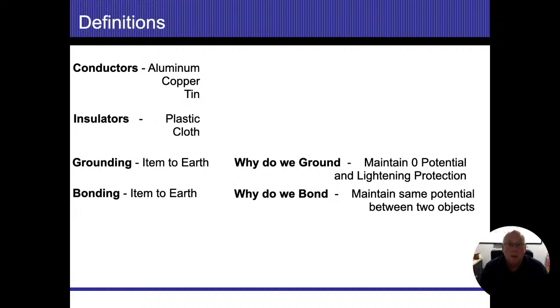It's wasting our bill. In fact, that's called a fault, more specifically a ground fault. Anytime electricity goes someplace that it's not supposed to go is considered a fault. And if it goes into the earth, we call those ground faults. All right. And I usually pop up another example, like I'll take a wire and I'll pretend that we're going to put this into the energized slot of an outlet. And let's say it's a 15 amp outlet. And then I'll take the other end and I'll go outside and I'll have a ground rod out there all by itself in the middle of the yard, driven into the earth, a good 10 feet in there.